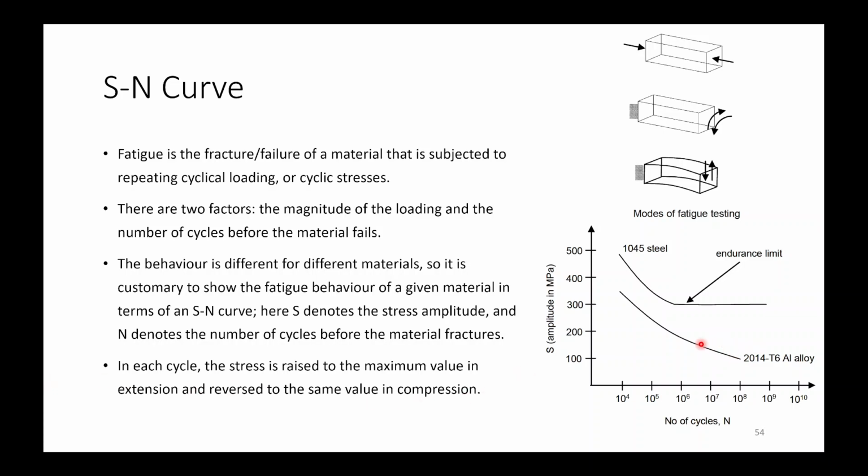So as I told earlier, in case of ferrous materials, you will have an endurance limit. Below this stress you can go up to a million cycles and you won't see failure in the material, while in case of non-ferrous materials you don't have this type of endurance limit.